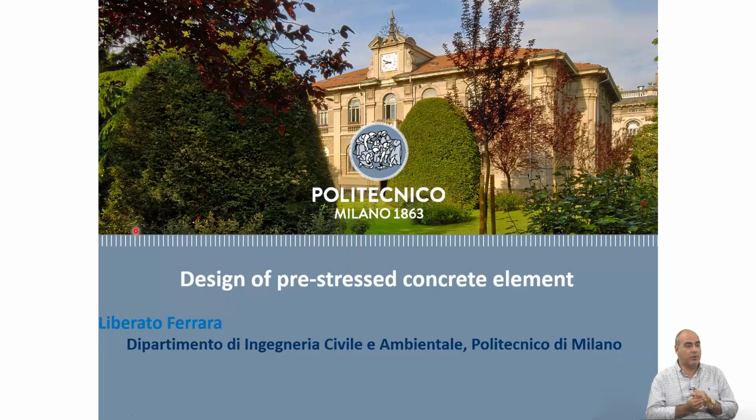Well, nowadays we have also other kinds of reinforcement, like the polymer bars and so on, which have the good property that they do not corrode, but they might have other properties. The bond is different, their modulus of elasticity is lower than that of steel. They tend to be brittle. Their fire resistance is not as good as the one of steel. So, in different situations, you might use a different reinforcement.